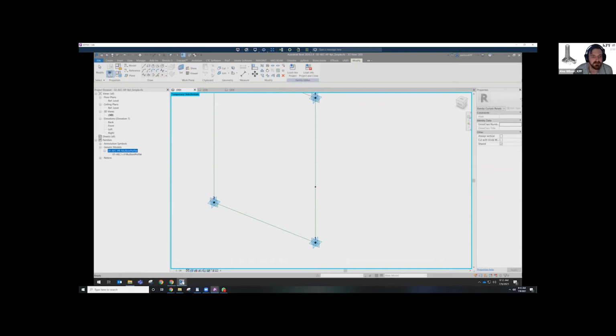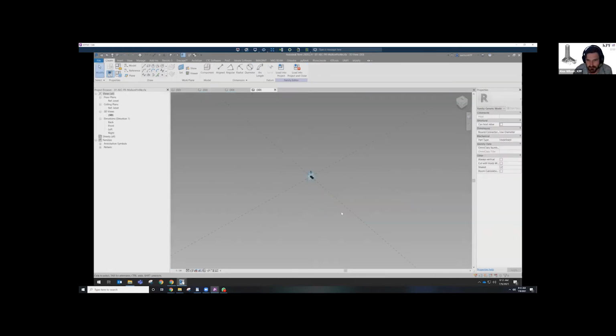You can see loaded into this panel, we have the mullion profile. If I edit this profile, you can see here, we have another adaptive panel. It's important to note that you can't load normal profiles into adaptive panels. Basically, the adaptive world is its own ecosystem that can live inside the Revit files, but you can't jump between loadable families and adaptable loadable families. They're just built different.